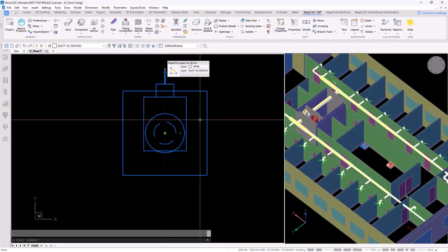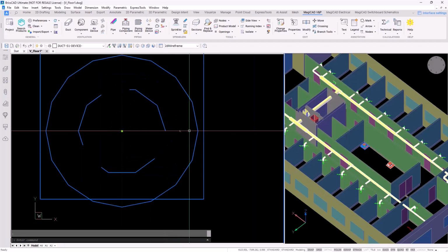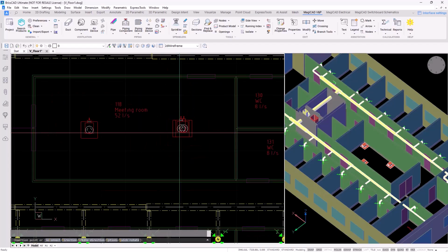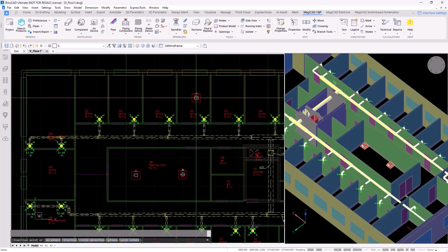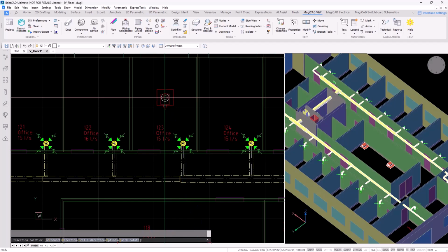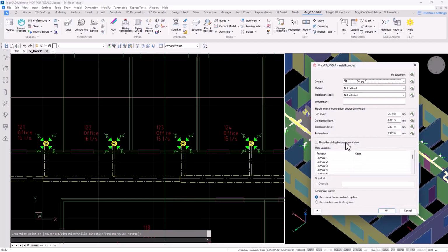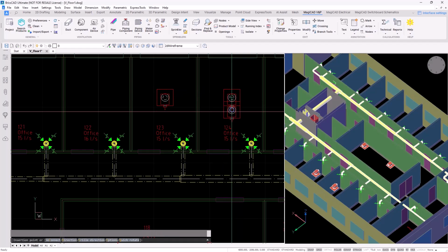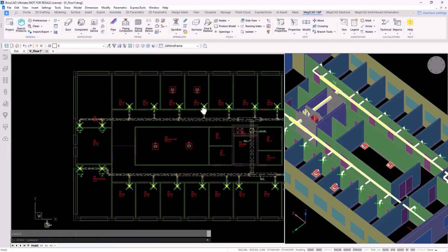There's the plus handle and this asterisk where we can create a new instance of the same device. Rotate it and place it again. Like this.